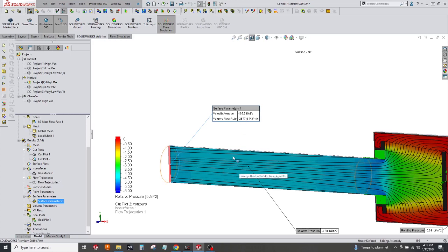Let's go ahead. I'll tell you what. I'm going to go ahead and chart this. I'm going to look at a few other scenarios in here as well. We're going to look at a little bit lower vacuum, and then something that might represent more like, rather than having this big, huge power adder that's going to create all this vacuum, maybe something more of like a naturally aspirated application where instead of this, we're looking at about 5 psi here, a little bit closer to maybe in the 1 psi range.